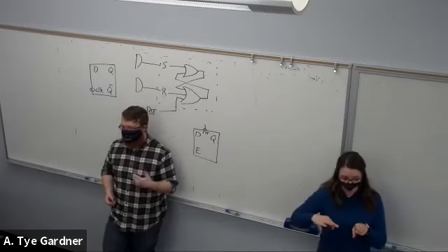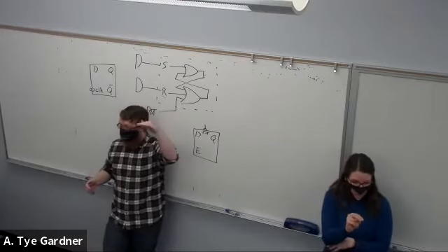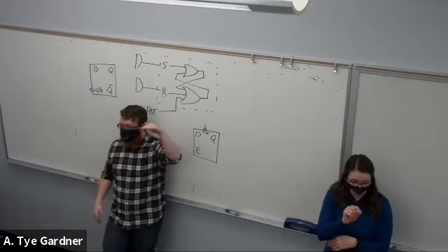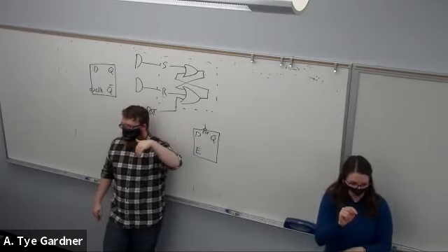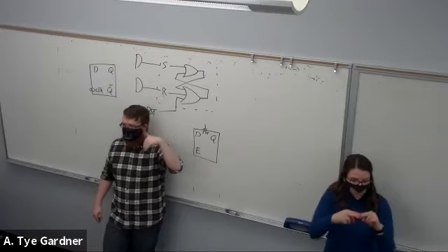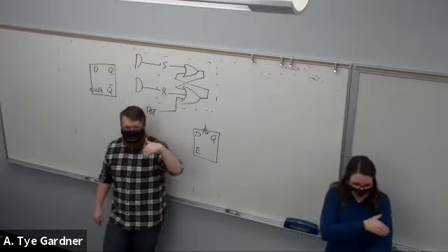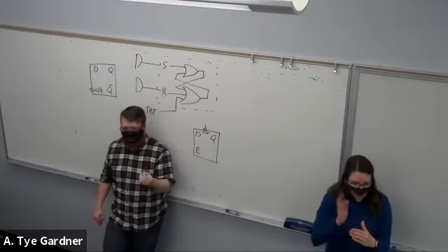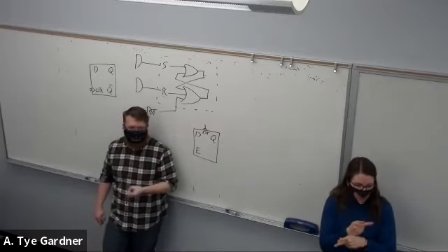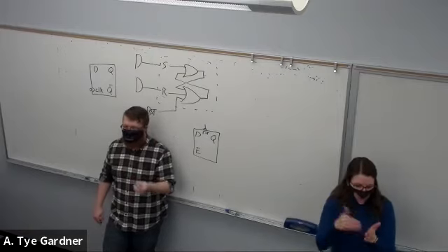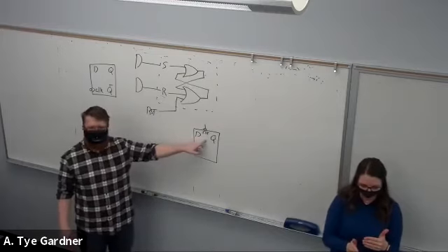Imagine a circuit that starts on, meaning the reset can be 1 and it's not resetting. But then you lose power and that drops to 0. Losing power automatically resets it, so it goes back to a predictable, well-defined state from where you can boot up. That means it's reliable to start up because you know where it ended. It makes life a little bit easier to have these active low resets.